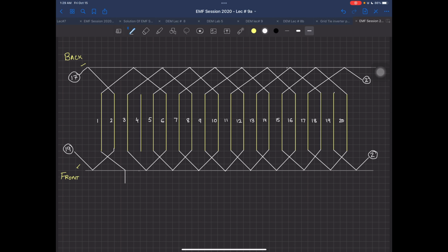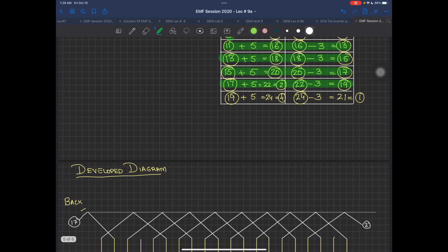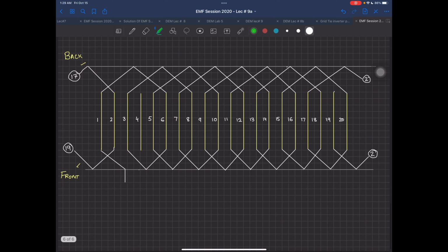which is going to go towards, if I go back on your table, this table is telling you from 19 to 4 this is going on. So from there, from 4 we have to go to 1, which will be the end of this winding. So this will be from 19. I'm again going to show it over here as an arrowhead, and this is going to be from 19 going on towards 4, and from 4 you can see very carefully that this is your 4th one, and this is going to tell you that this is your 19th connection coming on, because this is going to be a completed winding.